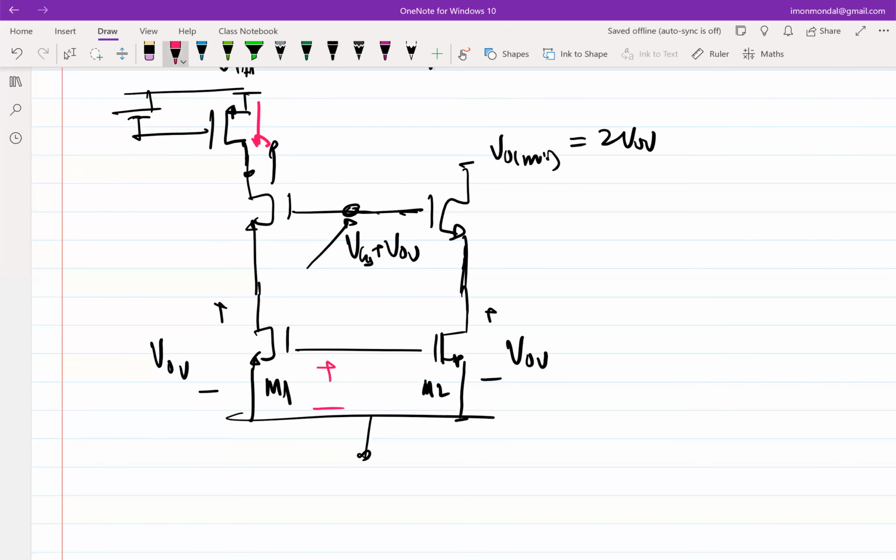Then this current source is trying to push in current and the bottom circuit is not able to accept it. So this drain voltage will increase till the PMOS goes into linear, and it essentially shuts out any capability of pushing current. It will still be on, but in the linear region, it will not be able to push in current of I0, right? So that's not going to happen.